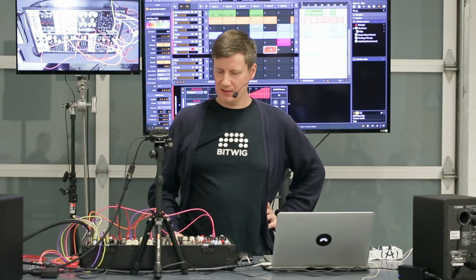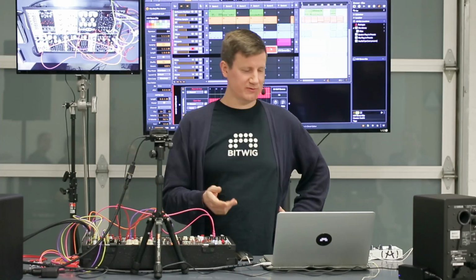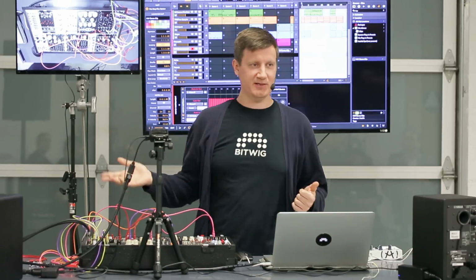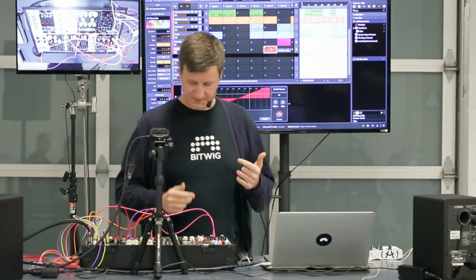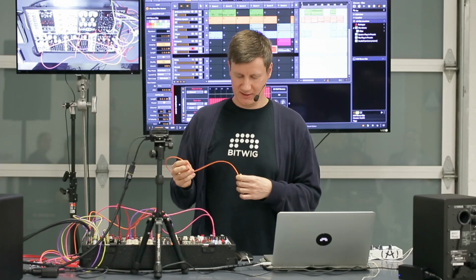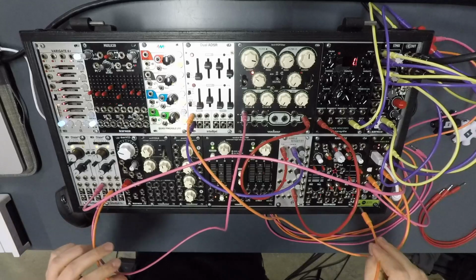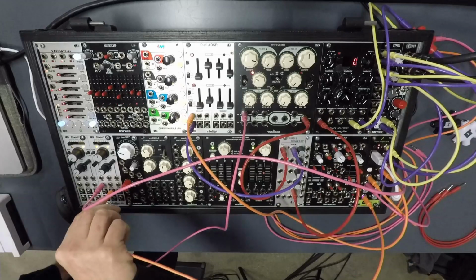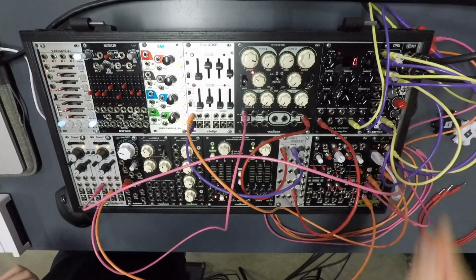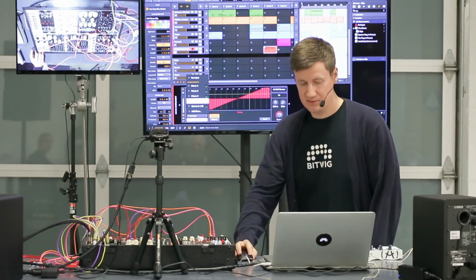Now, as you may have heard, or as you maybe know, analog oscillators are kind of dumb. They don't know what a note is. They don't know that I'm sending C4 or whatever. They just get some kind of electricity, and they spit out another kind of electricity. So what I can do is I can tune it and help BitWig Studio play the right notes to the oscillator so it knows what to play. I'm going to use an auxiliary or a secondary output of the oscillator and send it back into BitWig Studio. So I'm using a triangle waveform from the oscillator, sending it to an input in my audio interface. Lower the volume here so we don't hear it too loud, choosing which output that is from my chooser in the CV instrument.